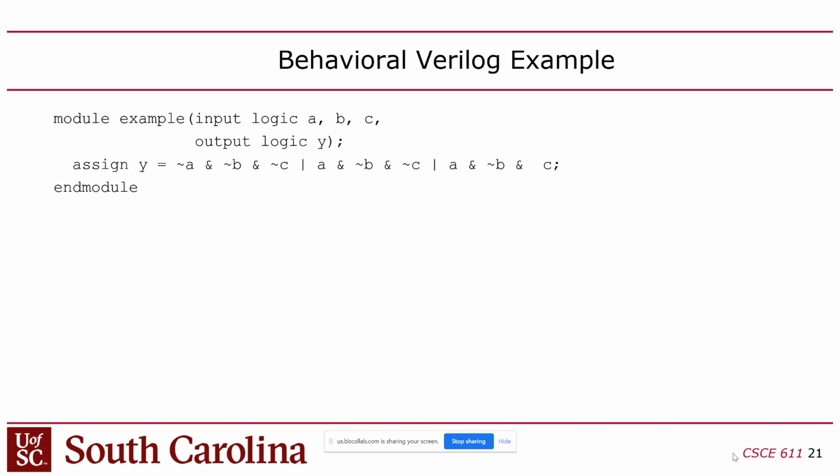Yes? What about variables, when they can serve as input and output? An input-output variable? Yeah, for example, modules with memory. If they have memory, they might trigger themselves. Yeah, if there's a cycle that breaks it. You're right. If you have a register, you can have a circular dependency there because there's memory involved. But in this case, I'm only talking about combinational logic. When we get to memory, I'll explain that the event that triggers it is actually the clock and not the inputs. But because this is combinational logic, anytime one of the inputs changes, it'll trigger that output right away.